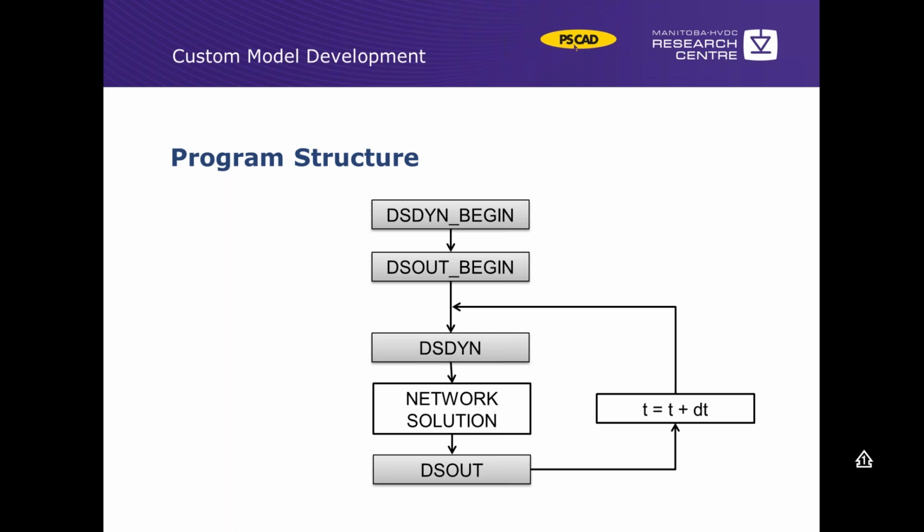So if you look at this slide, DSDYN begin and DSOUT begin, they are executed only once. So that means these are the ideal place if you want to do a one-time computation and then use that later in every time step.